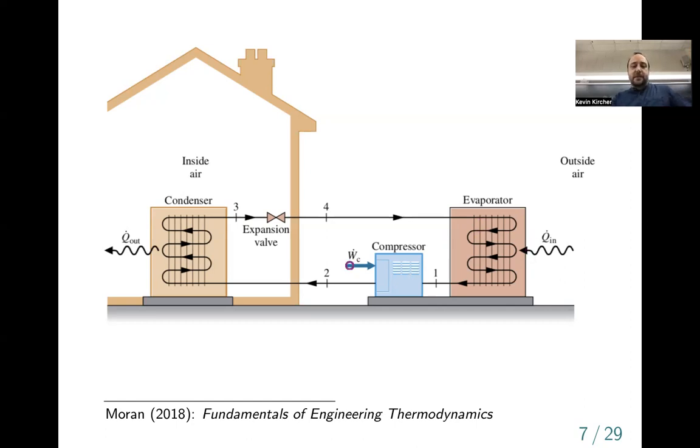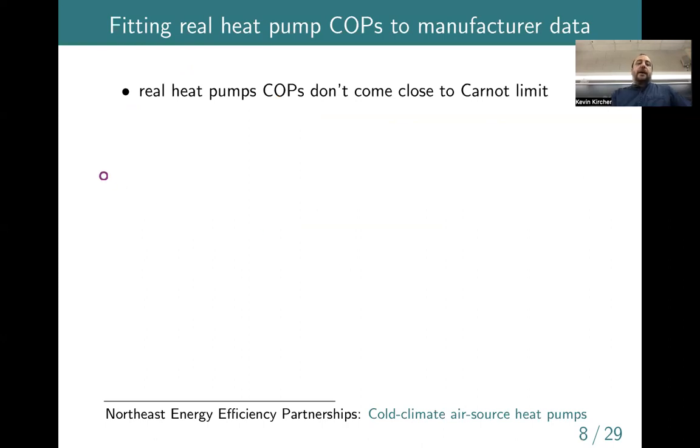And they're using different symbols here. The W dot, that means work or typically electrical. Okay, so we talked about a sort of theoretical, nice, smooth performance curve, the Carnot performance limit. But actually, real heat pumps are nowhere near as efficient as a Carnot, a theoretical heat pump. And so typically when we're doing modeling, trying to understand, say, how much electricity a house is going to use if it's using a heat pump to stay warm, we need to typically look at some real performance data.